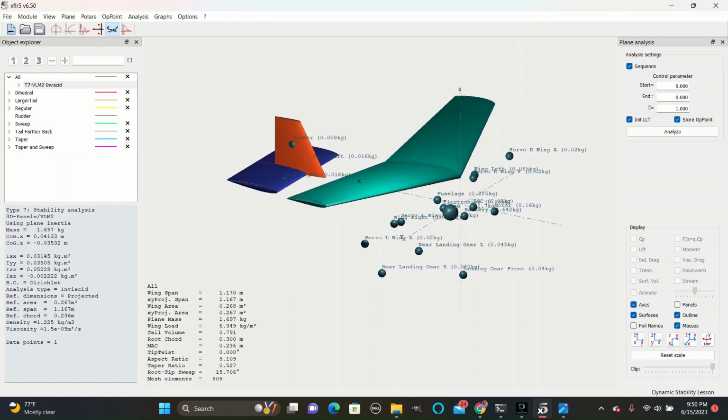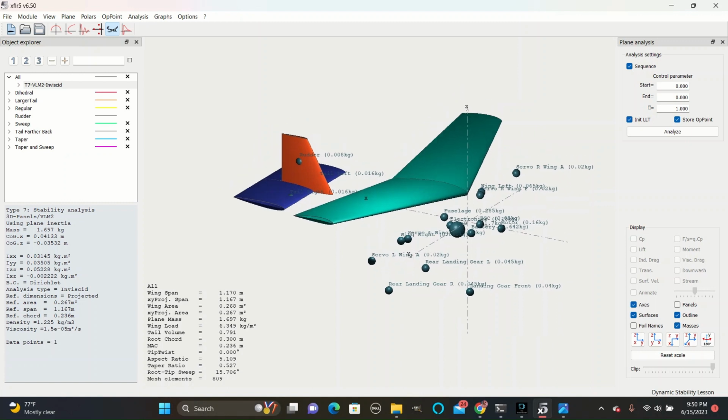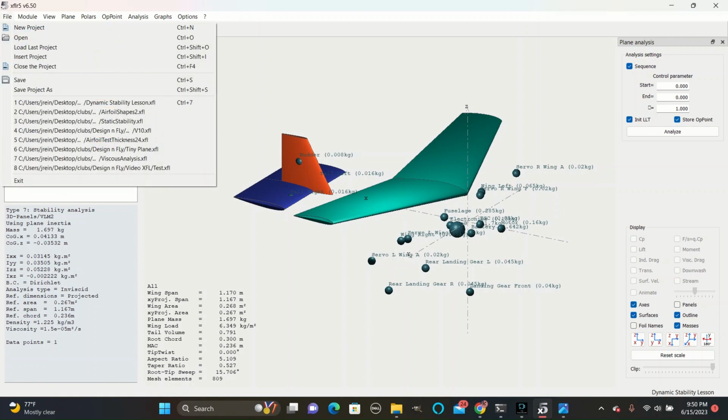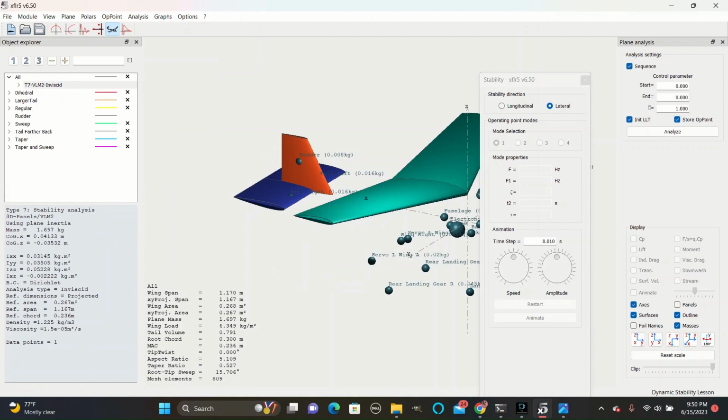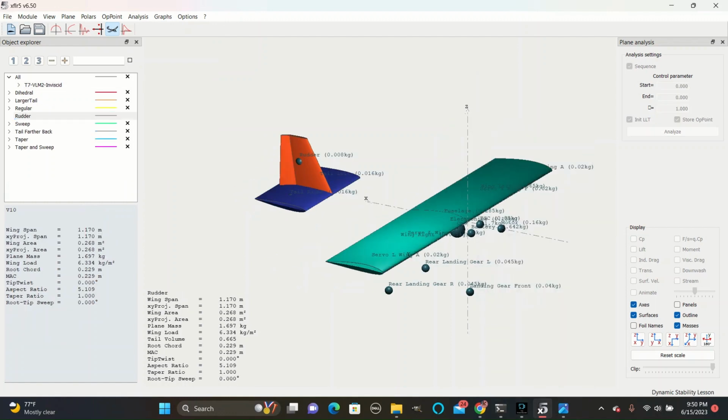The horizontal stabilizer is the horizontal surface that balances the plane and is usually synonymous with tail. However, tail can refer to this entire section that also includes the vertical stabilizer. The vertical stabilizer is used to stabilize the plane's yawing, and the rudder is located on the vertical stabilizer to allow the plane to turn, which you can see pictured here and here, as they are both turned as opposed to blending with the rest of the airfoil shape.